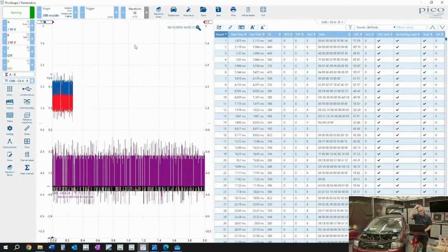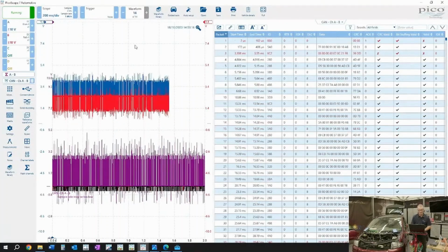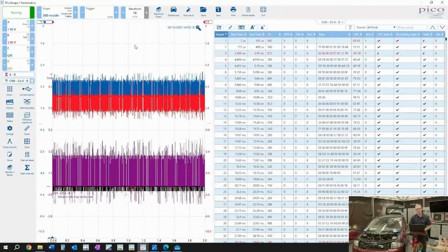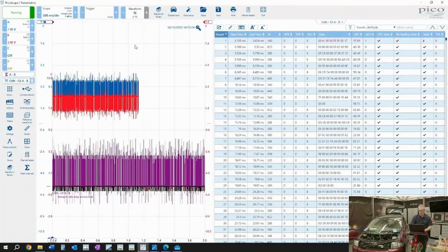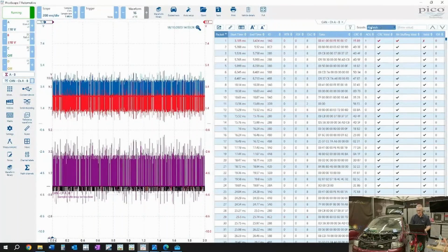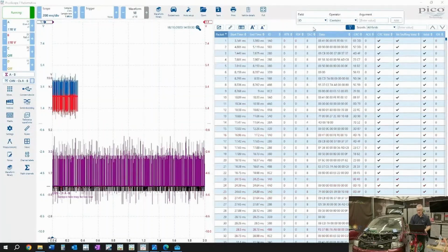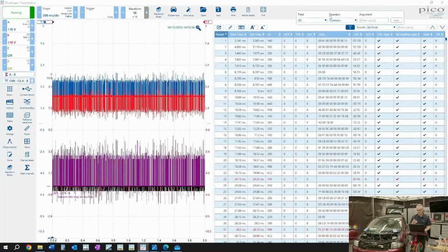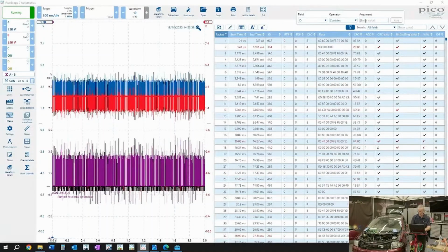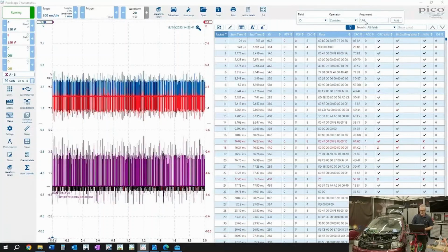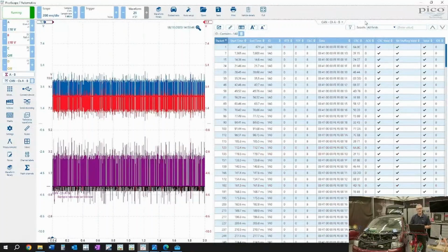Reverse engineering. Now, we happen to know on this vehicle that the ID for our ABS ECU is 1A0 in hex, so 1A0. So we can search for that. We've got search tools here. We'll click on the search icon. The field we want to search on is the ID. The operator is "contains", in other words, we want it to contain the following digits, which is 1A0. You'll notice now the decode table is only showing 1A0.